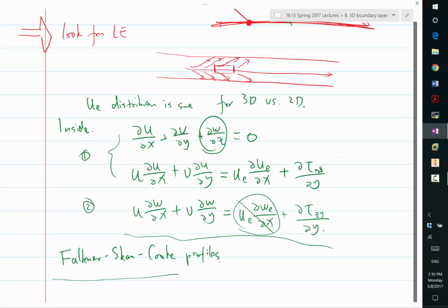So changing the velocity by 20% doesn't really change the turbulence that much. So you can pretty much use the same turbulent viscosity, which is still going to be the same. So even in turbulent cases, we can comfortably make the approximation that we can solve for 1 first and then solve for 2.